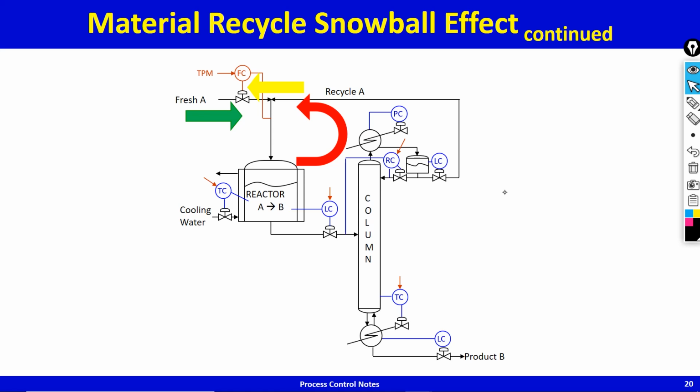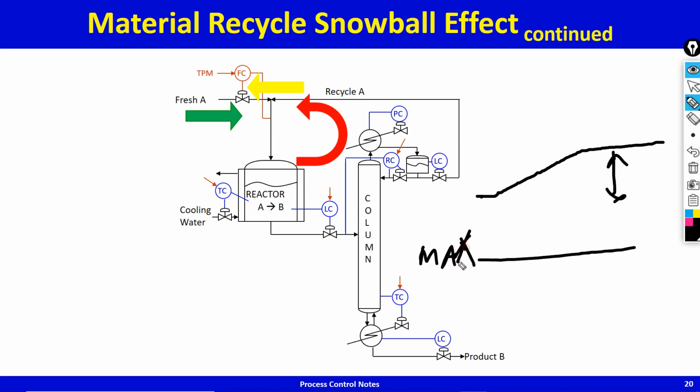That being the case, now let us say the management, same management with this control structure, comes to the operator and says crank up production. Now you see, I can crank it up gently. I can crank this up, the total flow rate set point, gently, and take it close to whichever is the unit that hits a maximum limit. So let us say the column flooding is the unit that hits maximum limit, and variability in the column vapor rate is this much.